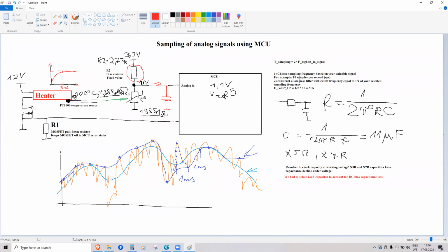Let's say we want to produce 10 samples per second, but what happens if I sample the signal, and even though I have this low pass filter, right at that moment maybe somebody turns on some motor in the grid, or maybe the electricity makes a little bump or falls for a small period of time, or maybe lightning strikes next to the house, and there's a little spike up or a little spike down. This capacitor has some internal resistance, so it cannot filter everything in the world.